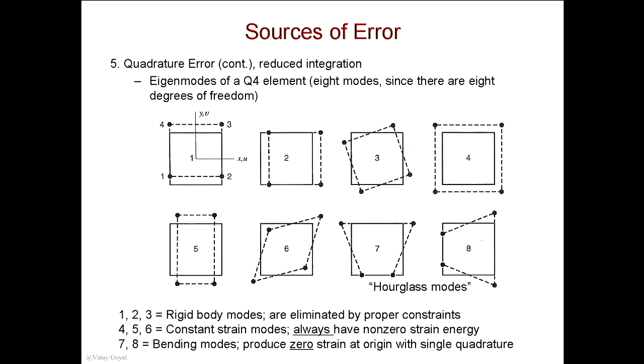If I plot that, I get a rigid body motion along V. Makes sense, I should get a vertical motion. I get the axial motion of this element. That makes total sense. Or I have a rigid body rotation. Makes perfect sense. So these three can be suppressed, and you suppress them by prescribing boundary conditions to your model. If your model is not properly fixed, you should try this in Abaqus: don't fix your model and run it statically. You're going to have singularities and a bunch of issues. So look at the dot message file. Take some of the models that we discussed in class, don't fix them, and do a static calculation. You're going to see that the model is going to go haywire. It will give you some errors.